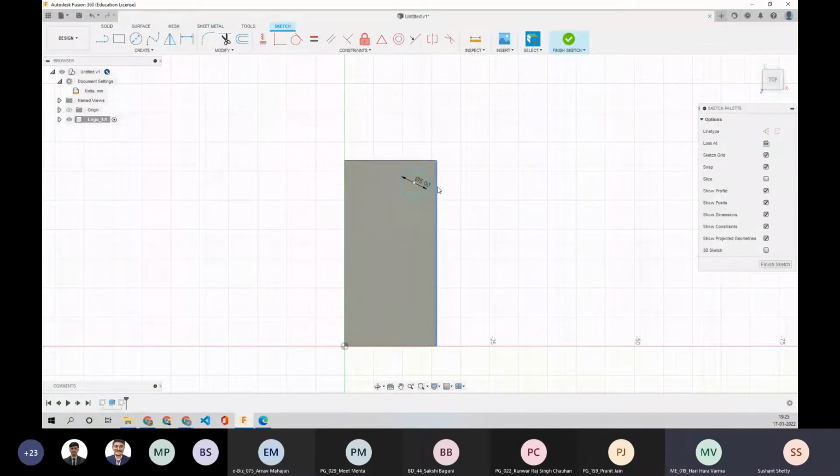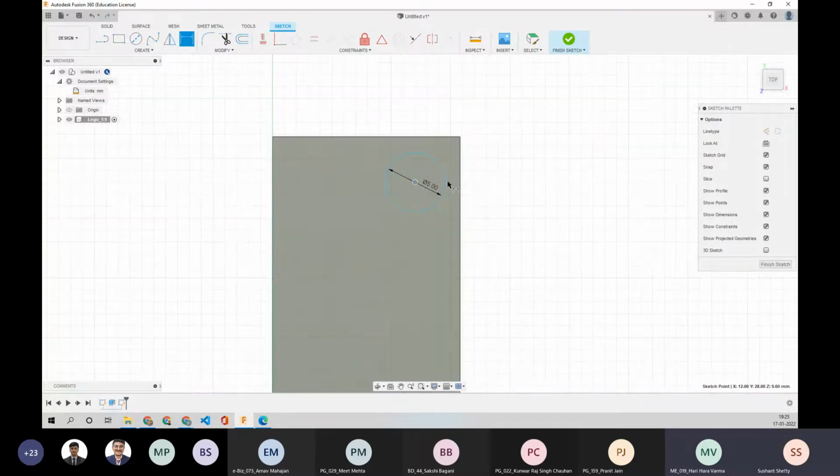Now what you want to do is set this at a distance of 3.9 mm from the edges. So you'll press D on your keyboard. You'll press at the center. I'll just zoom in, and you'll press here. So you see this is approximately 3.8. You'll just place this here, but you'll say 3.9. You see it's shifted. We'll do the same thing for this point as well. Select here. Okay, it's also 3.8. Even here you'll say 3.9.